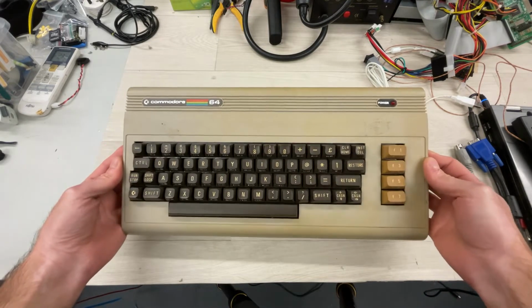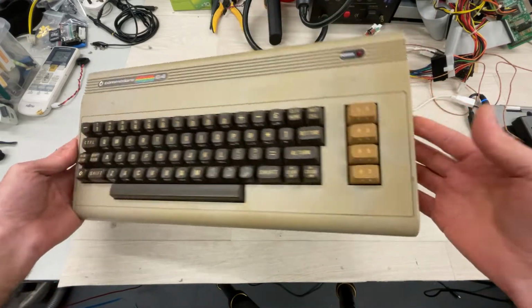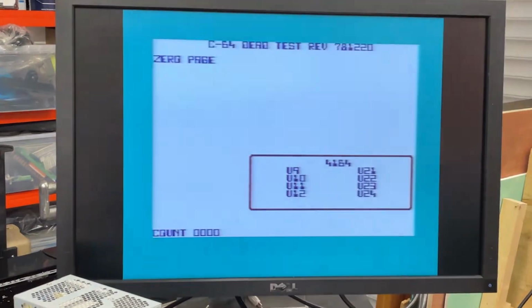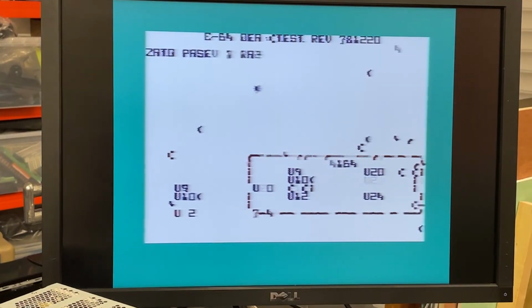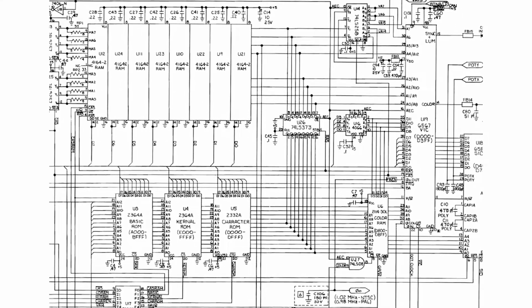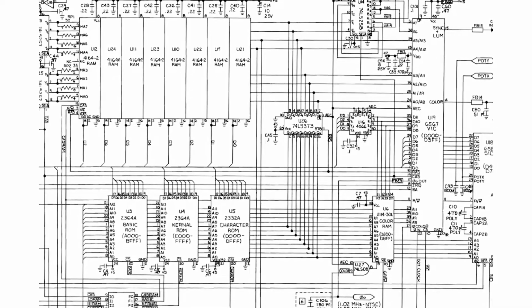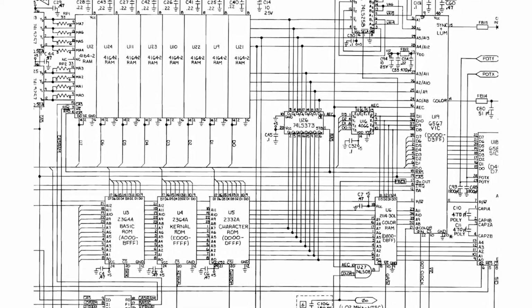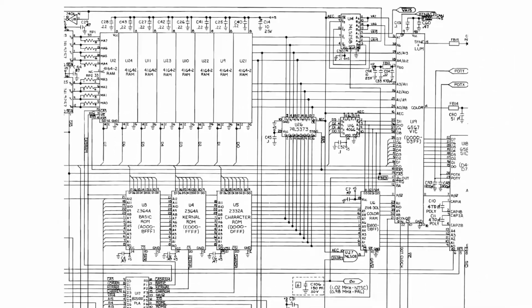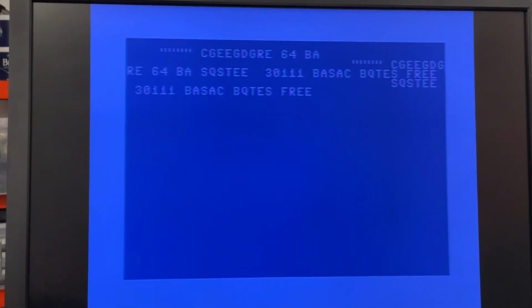In part 1, I showed you a Commodore 64 I purchased locally, which appeared to work at the beginning, but very soon showed a very interesting fault. I troubleshot the Commodore, blaming a stuck bit on the data line, or maybe the character ROM itself. In the end, I realized that a stuck bit on the data line would likely result in a boot failure, and an issue with the character ROM data outputs would probably result in graphic corruption on the characters, and not the wrong characters displayed on screen.